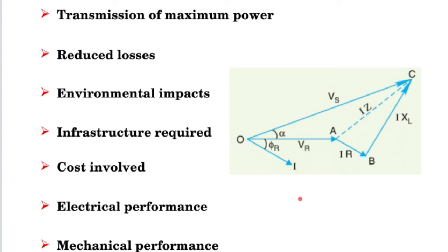There is no generator. We are only talking about the transmission line here. Sending end and receiving end is a transmission line conductor. It starts at the sending end and finishes at the receiving end. The phasor diagram only shows the phasor quantities for the transmission line, sending end to receiving end, nothing else. Generators are located at the generating stations, power stations, not in the transmission line.